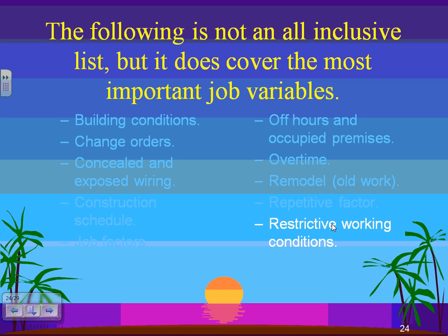Okay, so we have change orders. There's a few things I want to highlight from the book, guys. Okay, so the height. Take page 36 in your book. If it's 1 to 2 floors, you don't increase your labor unit, 0. If you go 3 to 6 floors, you have to increase it by 1%. I'm reading from the top upper left corner of page 36. If you have 20 to 30 floors in the building, you have to increase every labor unit that you install there by 13%. That gives you an idea, because it becomes hard to get into these buildings. So that's one.